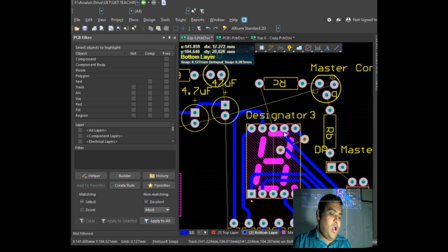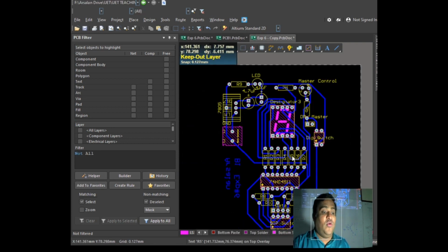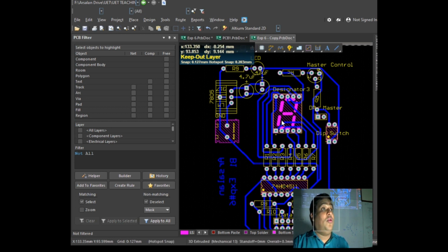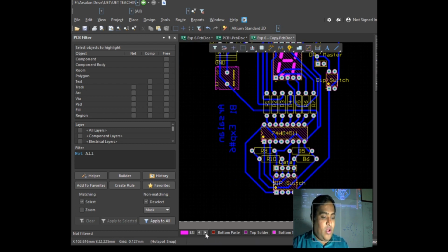Now coming on to the next part, please. The size of your PCB is going to be decided by your margins. Now how are those margins going to be added? I will come back to the strings and attached parts afterwards. Click on this one and select Keepout Layer.